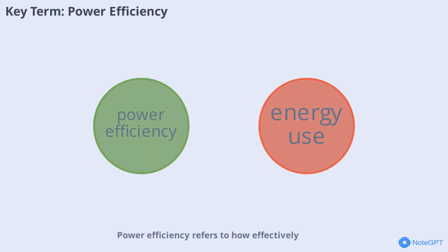Next, let's discuss the importance of power efficiency in AM. Power efficiency refers to how effectively a communication system uses its transmitted energy. In AM, much of the power is spent on the carrier, which does not carry information. Techniques like DSB-SC and SSB improve power efficiency by reducing or eliminating the carrier and one sideband. Power efficiency is a key consideration in designing modern communication systems.